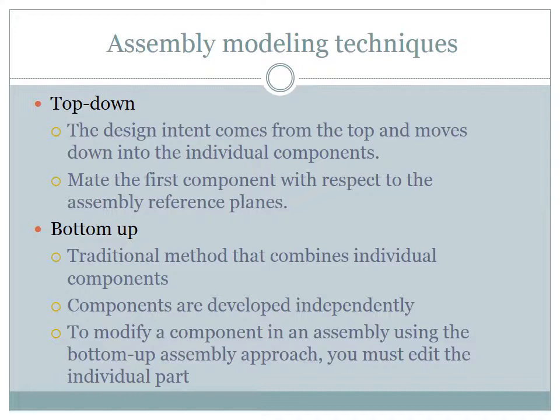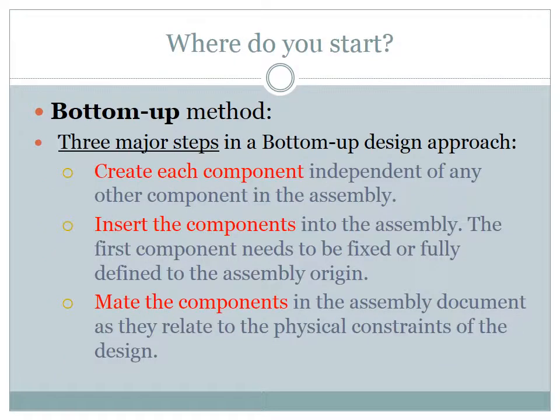I'd like to spend a little time talking about the 2 main modeling techniques we use, top-down and bottom-up. With top-down, the design intent comes from the top and moves down into the individual components. You make the first component with respect to the assembly reference planes. The bottom-up method is the traditional method, where individual components are developed independently. Then to modify a component in the assembly using the bottom-up approach, you must edit the individual part.